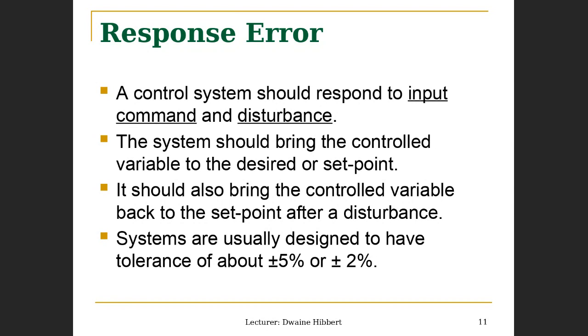Well, if it's a closed loop system, go ahead, please. I'd expect the drone to return to its original position, or do the calculations to return to its original position. Yeah, it should attempt to do so. At minimum, it should attempt to recover its original position. That's correct. So the drone should now recognize that it's been disturbed from its desired position, and should seek to regain that original set point. So it's now responding not due to a new input command, but to a disturbance.